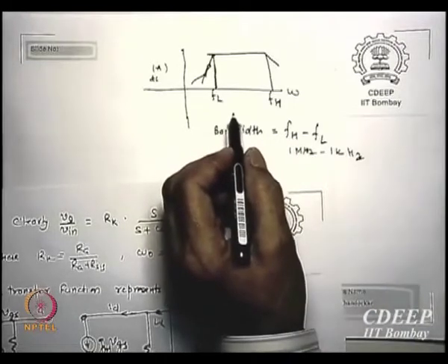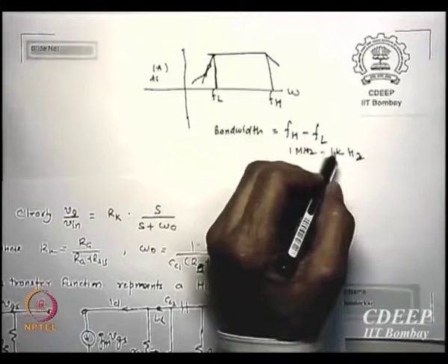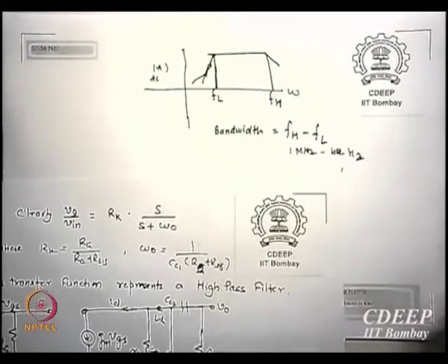But if FL is not very small, as we thought here, let us say it is 100 kilohertz, it is reducing substantially. So I must understand what is the value of FL before my assumption that the bandwidth is only FH, or otherwise calculate FL and subtract from FH. Numerically it may get subtracted or not. If it is very small, it will not be worth 6 decimal, or if it is equivalent, it will reduce the number in the first decimal. So we must evaluate every time, and numerically values sometimes may not be worth actually subtracting. But we must know what is the low value itself.